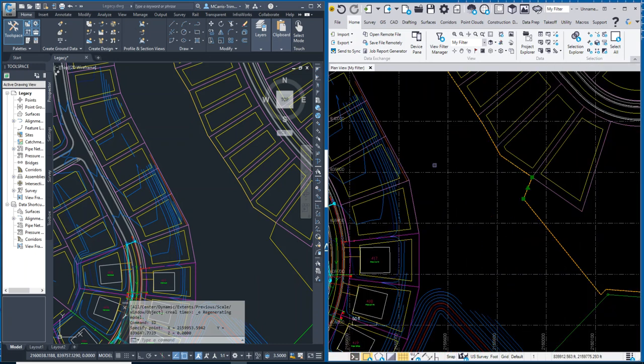So bringing a Civil 3D drawing into Business Center does not scale or change the objects, because the AutoCAD drawing header of the file does not indicate what type of units it is, whether it's feet, meters, or whatever. It's just basically X, Y, and Z. So when Business Center sees that there's no indication, it's basically unitless, so it brings it in as it was in Civil 3D.